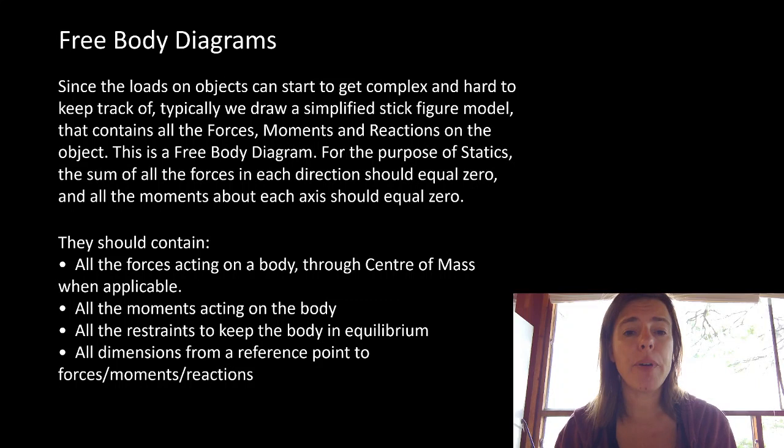So for every free body diagram, we need to draw all the forces and all the moments and all of the reactions on the system. Once we've done all that, we've kind of drawn a free body diagram. For statics, which is what we're studying, the sum of all of these things in every direction and about every axis needs to be zero. That's what we want, to know this thing is in equilibrium.